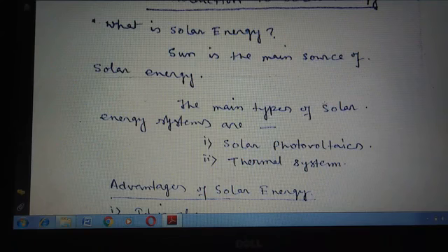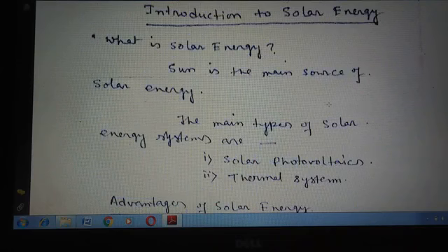Now, the photovoltaic technology. Photovoltaic or PV technology, or solar cells as they are also called, are semiconductor devices, because they convert sunlight into direct current or DC electricity. Groups of photovoltaic cells are electrically configured into modules and arrays, which can be used to charge batteries, operate motors, and power any number of electrical loads. By using appropriate power conversion equipment, a photovoltaic system can produce alternating current.